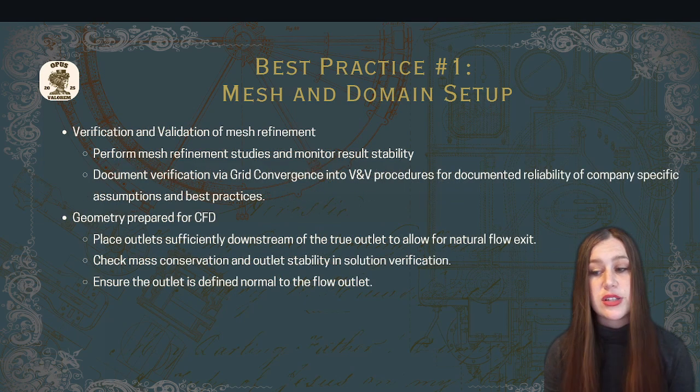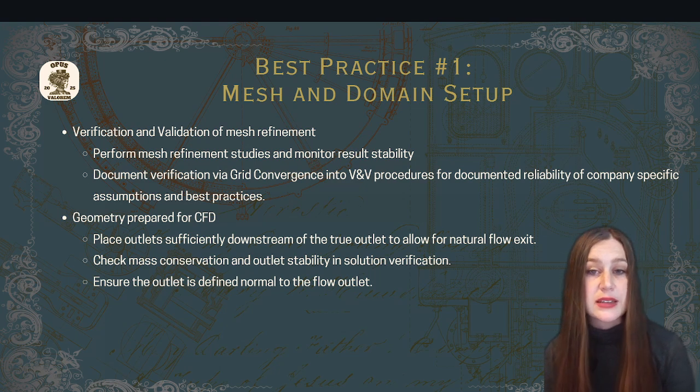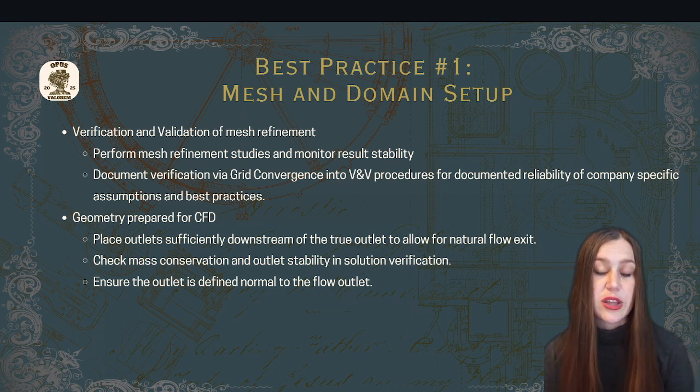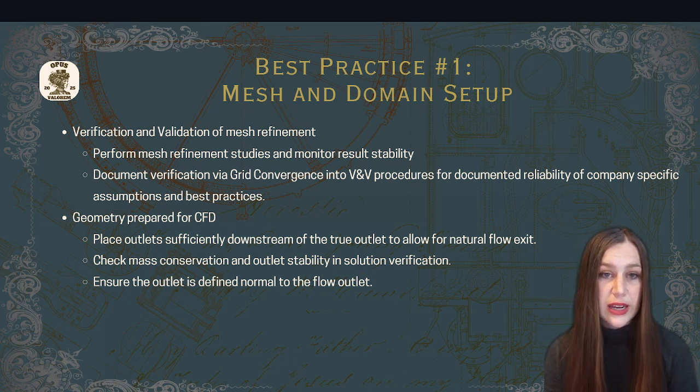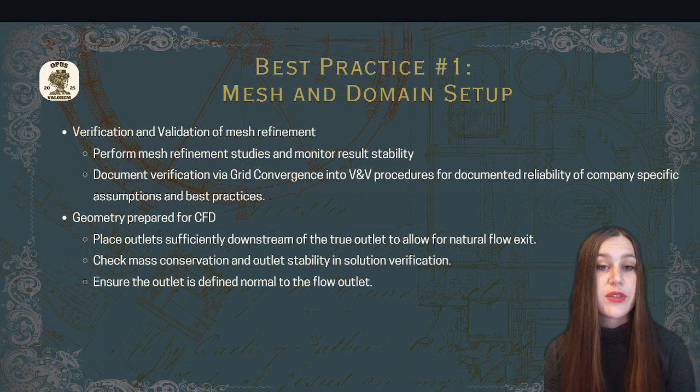You should verify that the solution is mesh independent by monitoring solution stability throughout mesh refinements. This should ideally be documented using the verification and validity processes of your company. To address your outlet, place the computational outlet sufficiently far downstream of the true outlet to allow for natural flow exit. Check mass conservation and outlet stability and ensure that the outlet is defined geometrically normal to the flow direction